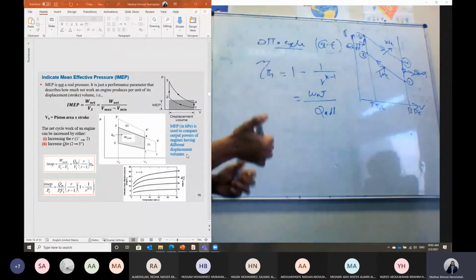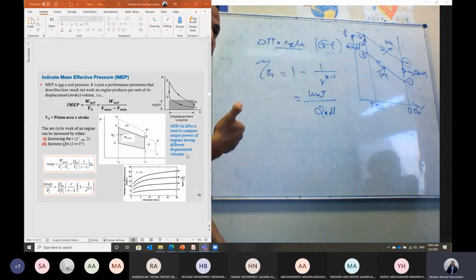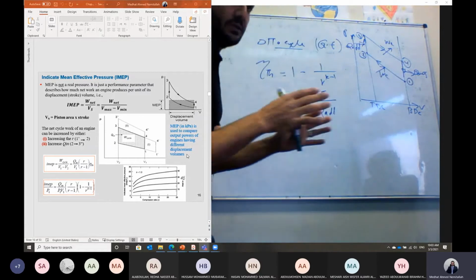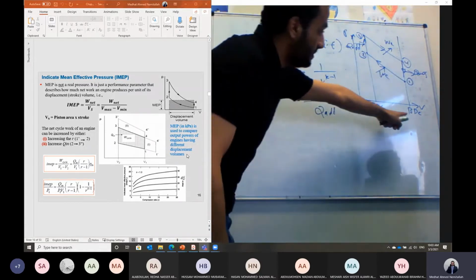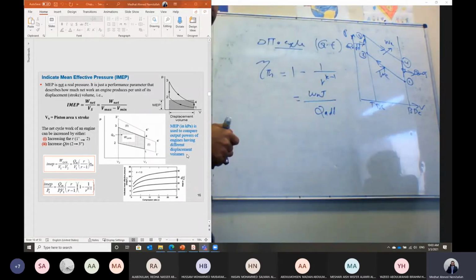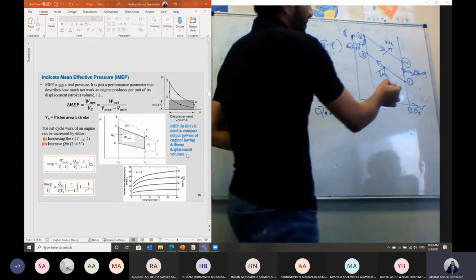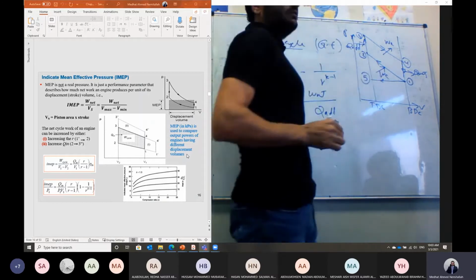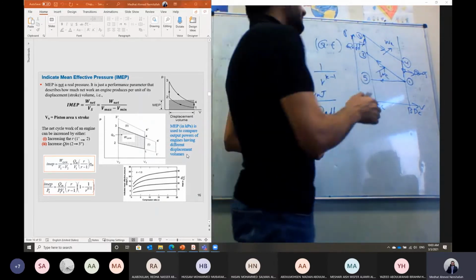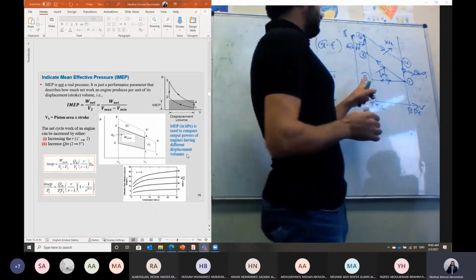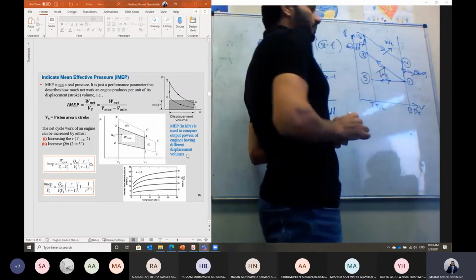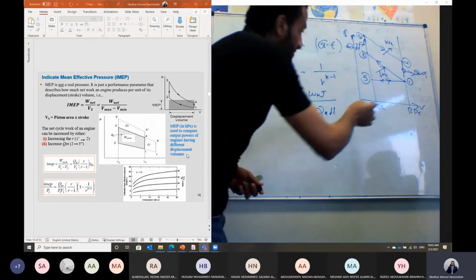Once we open the exhaust valve in the gasoline engine at constant volume, the exhaust gases, which are at high temperature T4, will be exhausted from the engine when the piston is at the bottom dead center, at almost no time. And then the piston will be moving from state 1 up to, let's say, state 5 to exhaust the gases, and then it will be reversed again from 5 to 1, from top dead center to the bottom dead center, and then we can have the intake stroke. But this is a process from 1 to 5.